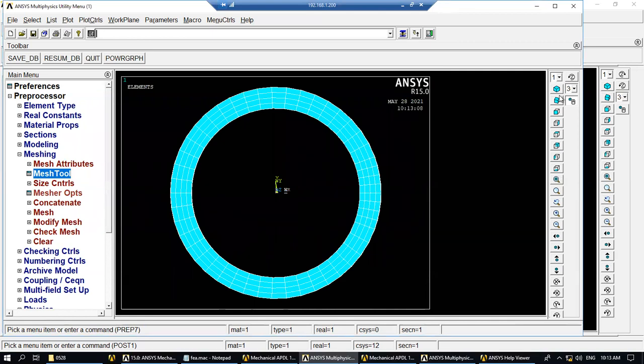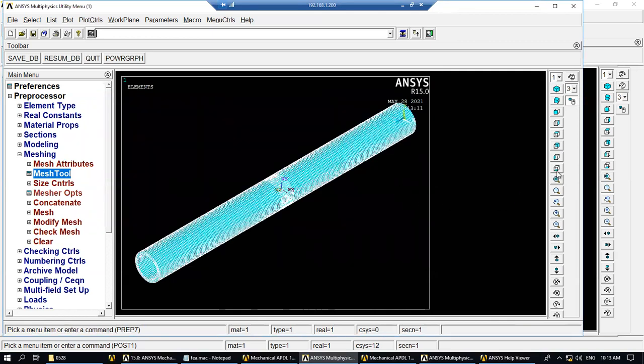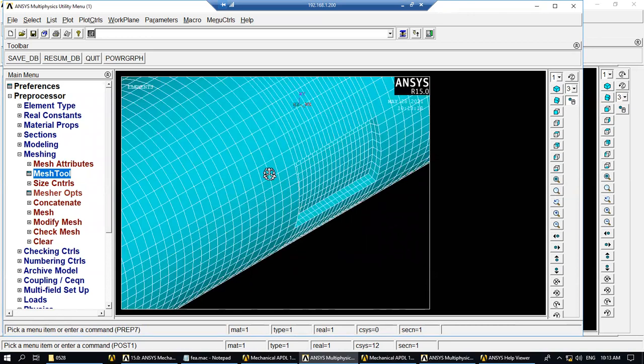Okay, it seems to look fine. So probably instead of 100 divisions for this length direction, you can use fewer there. You see, we say we have a good element if it is closer to a square. So probably you can have a little bit more. So the aspect ratio A and B is better to be close to 1.